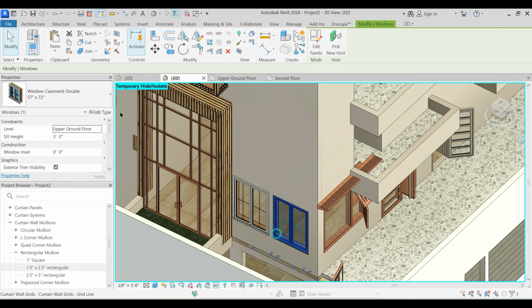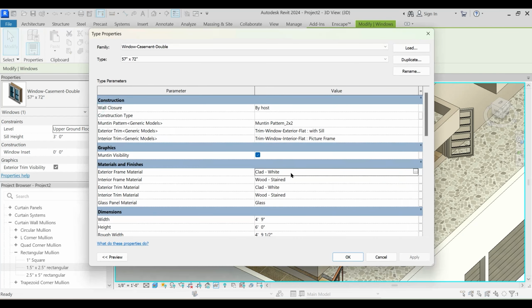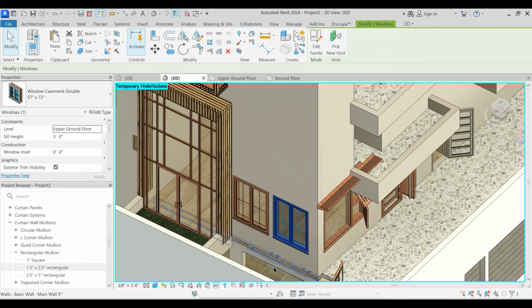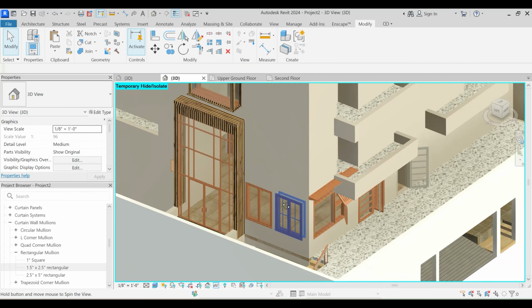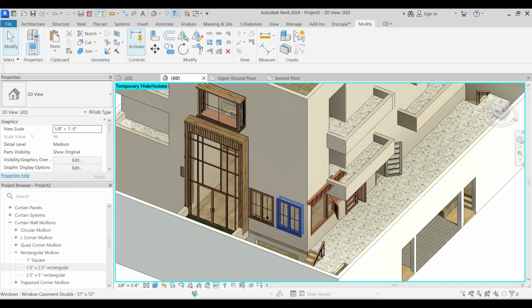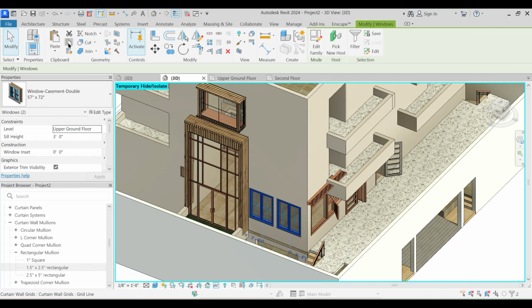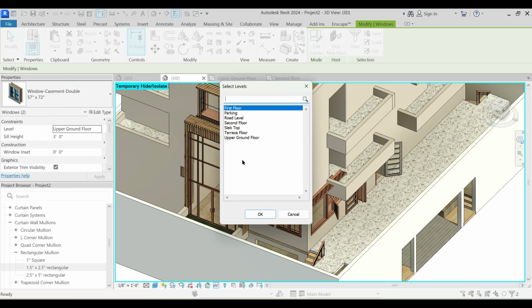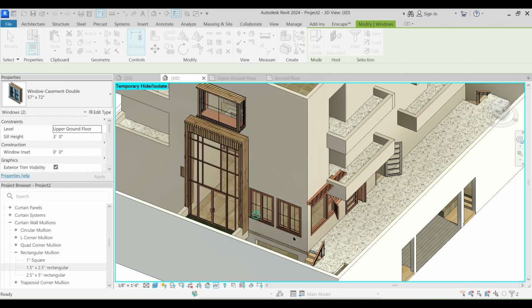Okay, so I need to go to this and change this 1 and 2 to sash. Copy, paste, apply and okay. Now I'm going to show you how you can use the tricks of modeling skills of Revit elsewhere. So 1, 2, copy, align to selected levels, and 2, first and second both.